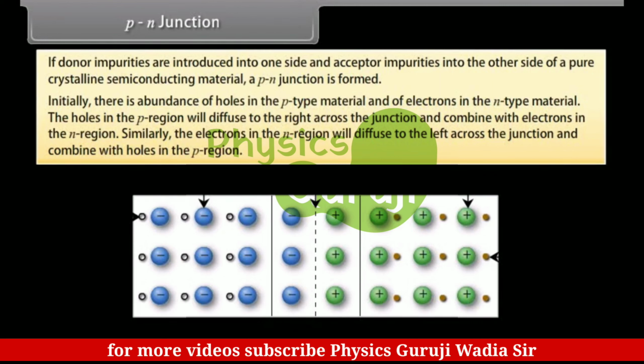Initially, there is an abundance of holes in the p-type material and of electrons in the n-type material. The holes in the p region will diffuse to the right across the junction and combine with electrons in the n region. Similarly, the electrons in the n region will diffuse to the left across the junction and combine with the holes in the p region. For every such diffusion recombination event, the left side of the junction acquires a negative charge and the right side a positive charge.